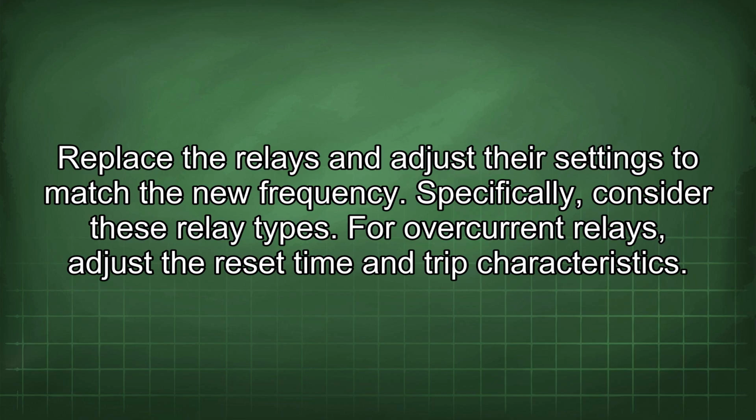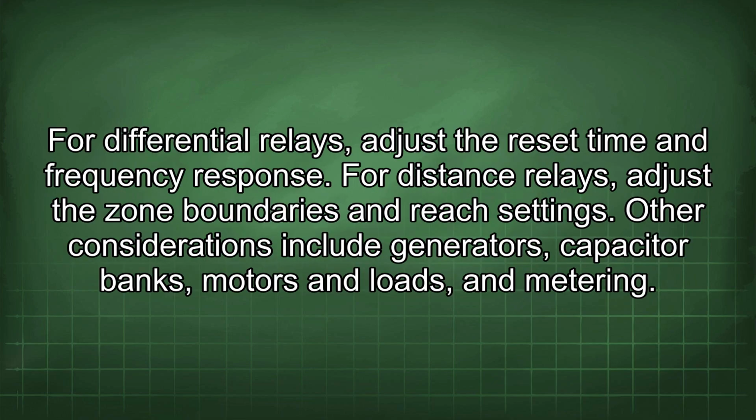For overcurrent relays, adjust the reset time and trip characteristics. For differential relays, adjust the reset time and frequency response. For distance relays, adjust the zone boundaries and reach settings. Other considerations include generators, capacitor banks, motors and loads, and metering.